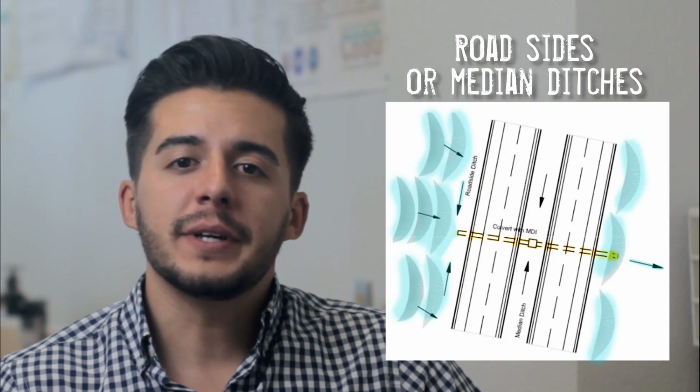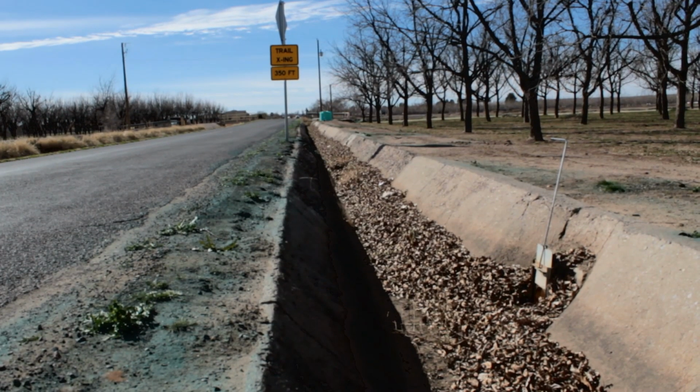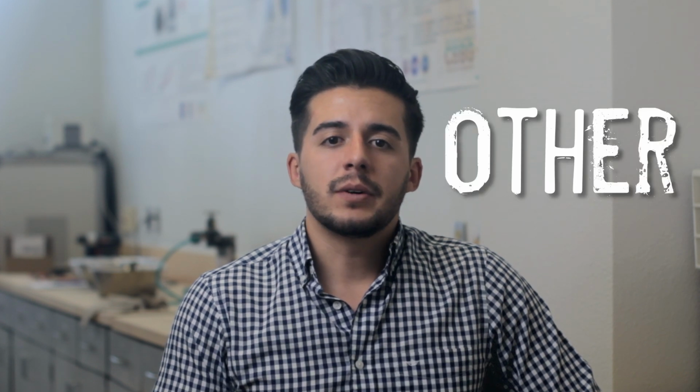Select roadside or median ditches if the primary drainage is from within the right-of-way of the road. If you see a concrete structure like this one, you will select concrete or asphalt line. If you notice that the channel is used to water crops, then select irrigation. As we always mention, if the channel doesn't fit any of these categories, mark it as Other. But wait, there is more.